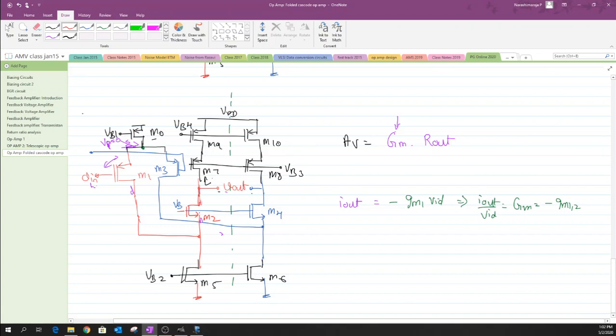Yeah. So now again, let us look for the impedance that is seen through the drain of M7. Since we know that M7 is stacked on top of the drain of M9, we first have to evaluate the drain impedance of M9, which is nothing but RO9. So there is an impedance of RO9 here, and when we look through the drain of M7, it gets magnified. Let me write that impedance as RO9 magnified by the intrinsic gain of M7, which is GM7 and RO7. Okay, and it's an approximated quantity, and that goes in parallel with the downward impedance.